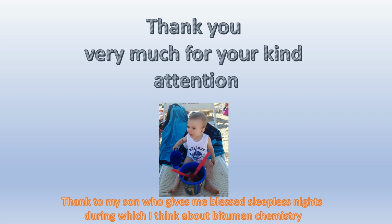So just to mark, this topic is very new in the chemistry of the bitumen, and there are some experiments in progress to try to understand the mechanism of this technology. In our opinion, we have to look at the surface property of the bitumen in terms of the polarity and dispersion of the surface, to understand the interaction between bitumen and aggregate. The scratch test is also very new, because nobody did it until now, and by the profile of the curve that I showed before, it is possible to understand the interaction between bitumen and aggregate. This topic is very important, it is the principal key of this mechanism.